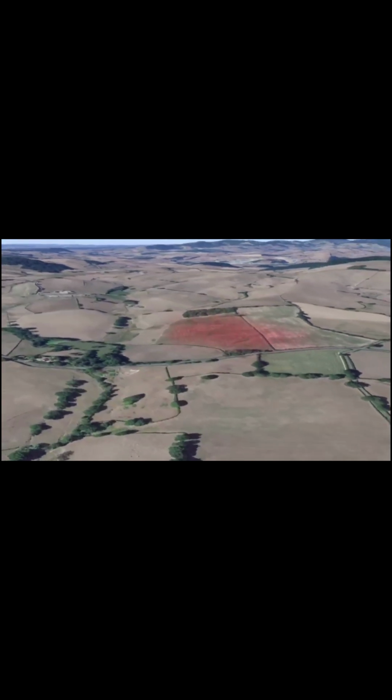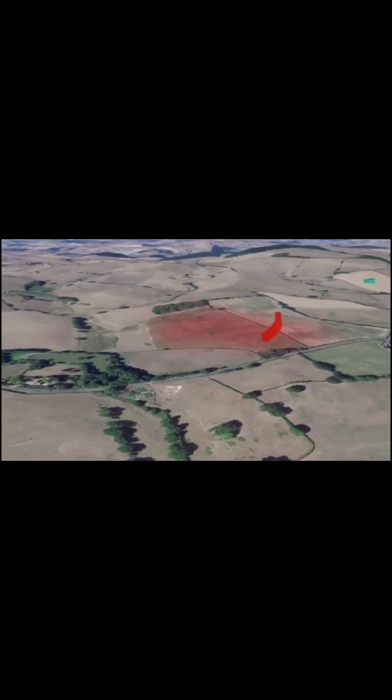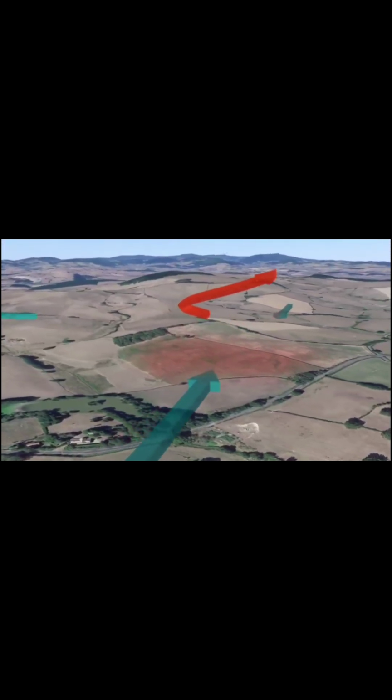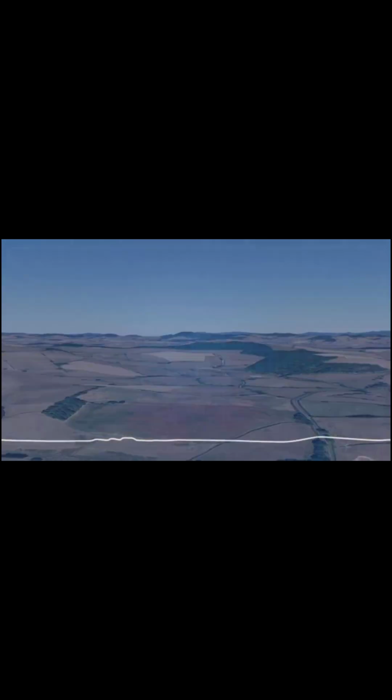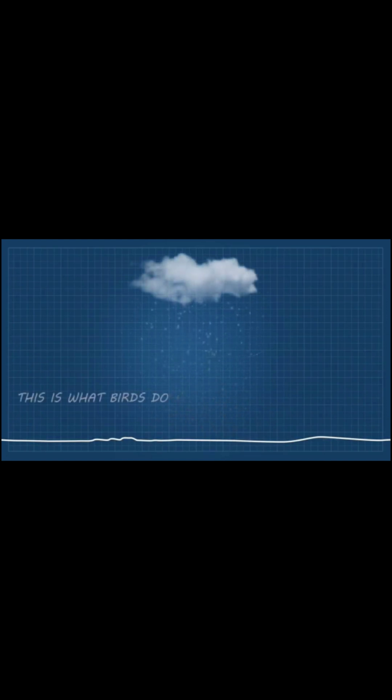Thermals are the most commonly mentioned way to gain altitude in a glider. These are columns of hot air that are generated by the surface heated by the sun. This air becomes less dense than the surrounding air and begins to rise rapidly. The glider, when entering a thermal, can begin to fly in a circular pattern to stay inside it and gain altitude until the thermal disappears or weakens.